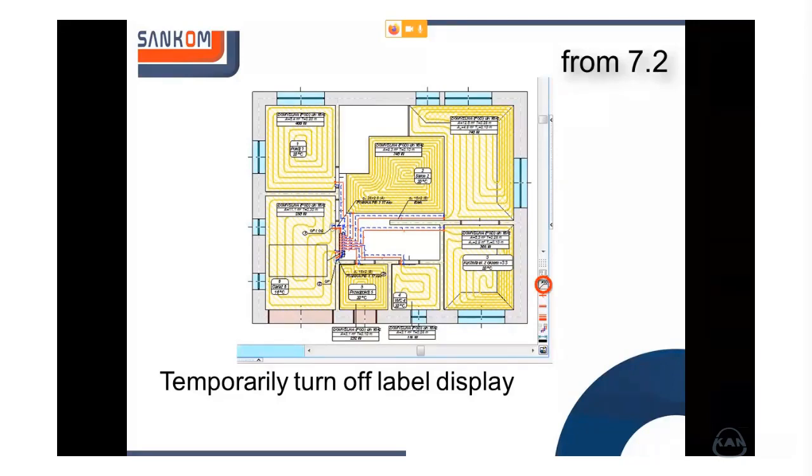When I consult on designs, very often my remark is that there should be more labels, especially on practically all, or the majority of, the accessories. Also, if you have manifolds, especially with underfloor radiators, they should also have labels that show the presets on the valves. So for the final drawing, it's good to have labels.